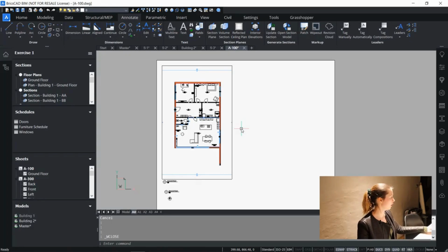And again, I will sum up what you can store. You can store title blocks, layers, colors that you imported, line types that you imported, hatch patterns that you imported, blocks that you created, text styles, dimension styles, and page setups. So basically a lot that you can specify. Certainly worth taking a look at if you want to customize your entire drawing process. A drawing template could be the solution for you.